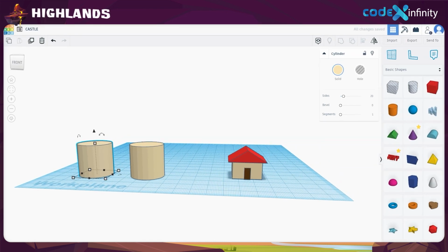Now let's adjust the dimensions of the cylinder and make it hollow to insert it inside the original cylinder to make the original one's interior hollow. So click on the white handle at the right bottom of the duplicate cylinder. Select the value of length to set it as 22, and press Enter key. Also click on the width value and assign it as 22. Then press Enter key. Let the height remain as default now and we can change it later if needed.